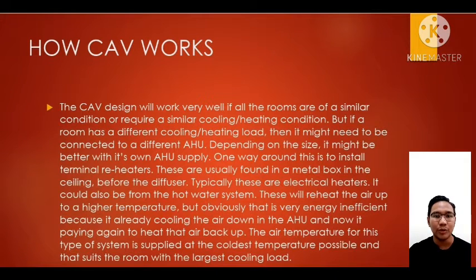The CAV design will work very well if all the rooms are of a similar condition or require a similar cooling or heating condition. But if a room has a different cooling or heating load, then it might need to be connected to a different AHU, which is the air handling unit. Depending on the size, it might be better with its own AHU supply.